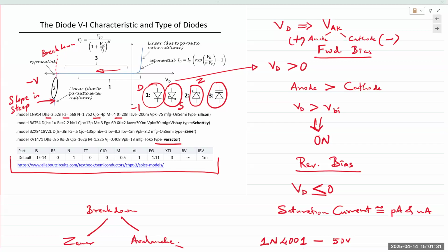Capacitance has the property of storing opposite charges on opposite sides of a barrier. And so the energy stored in that space charge region, the charges that are stored, can be modeled accurately by modeling it as a capacitor. And so that is known as the junction capacitance, CJ. Okay, junction capacitance, CJ.